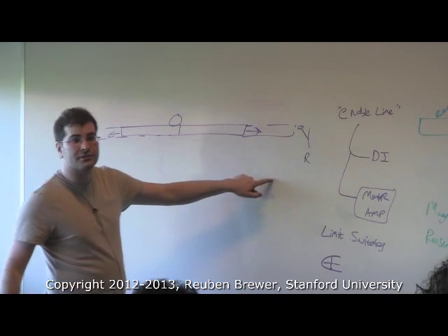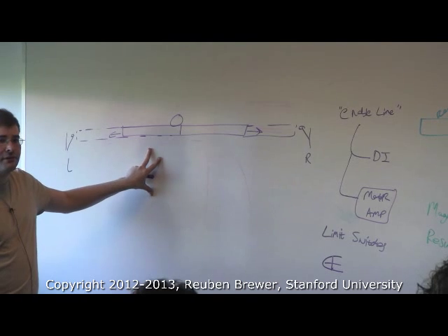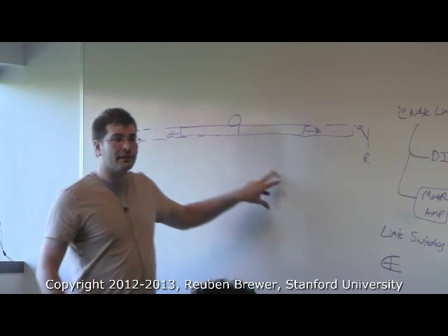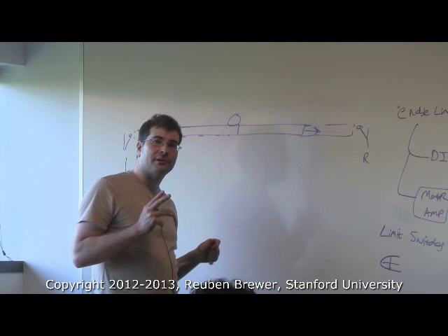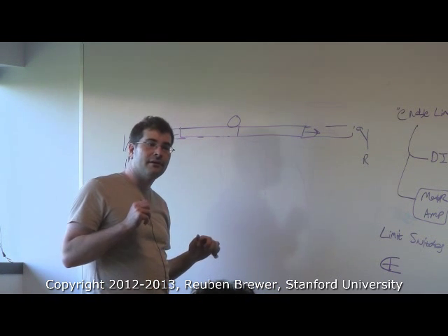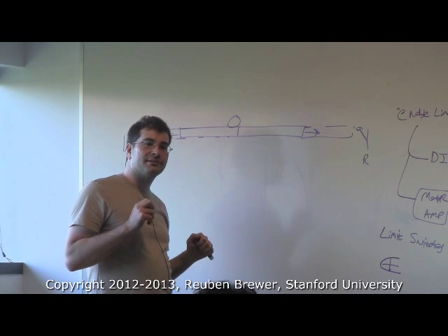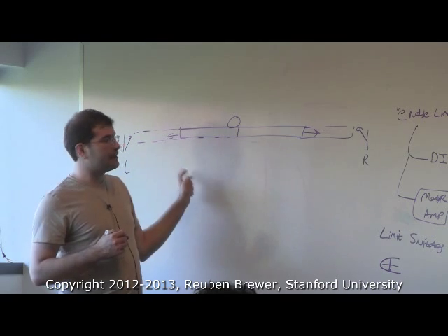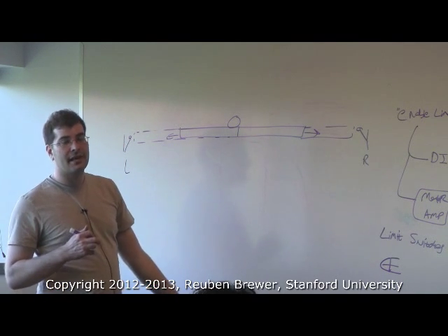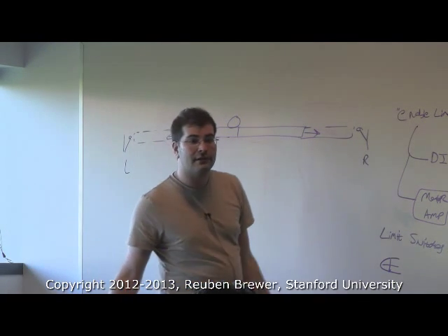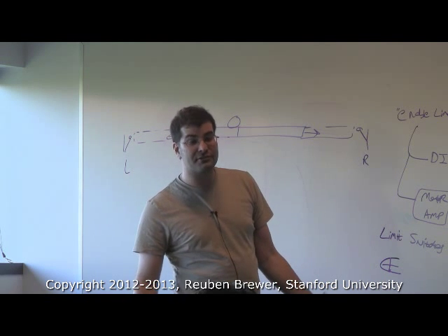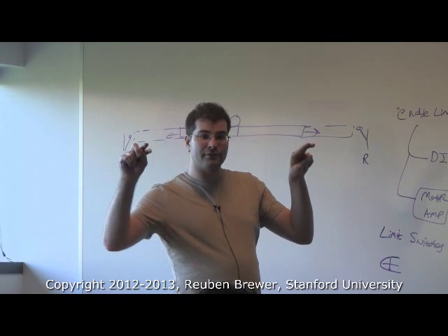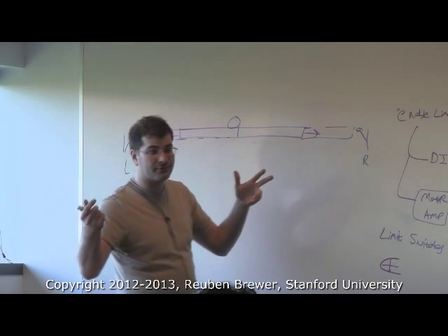Now the limit switches are mainly to prevent destruction of your mechanism. Part of the reason why Copley amps are so nice is they have an enable line and they have a left and right limit switch built in. And you can program them to do whatever you want. They don't have to be enable or limit switches. They're intended as such, but you can flip the polarity. Maybe 5 volts is on, maybe 5 volts is off.